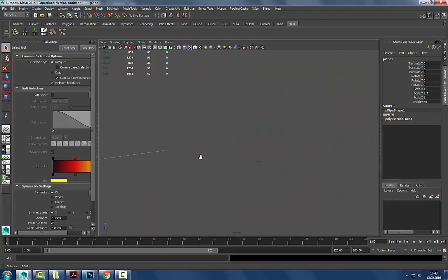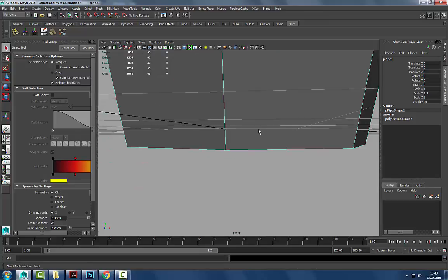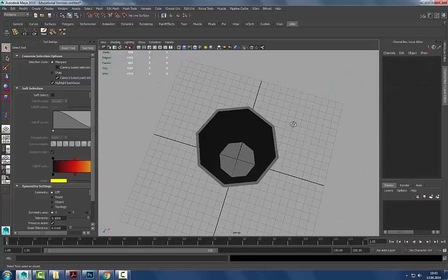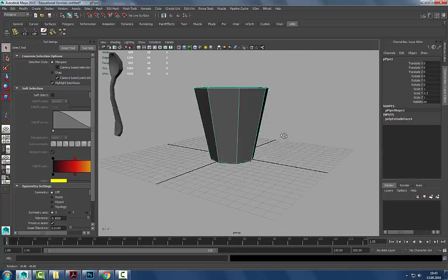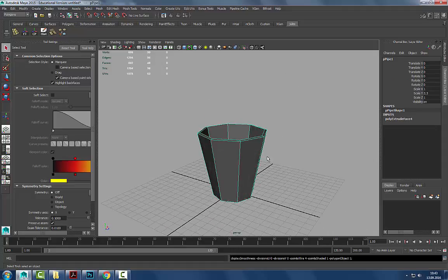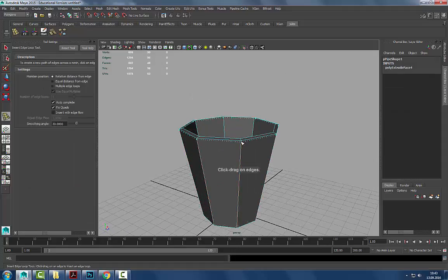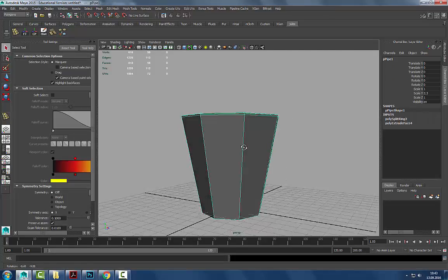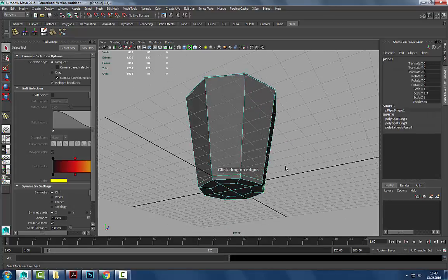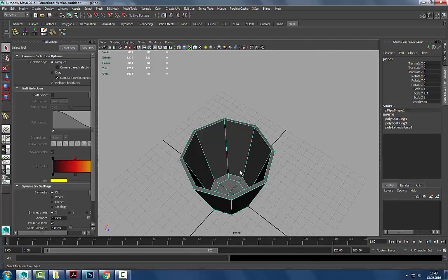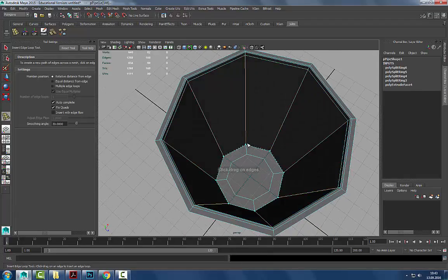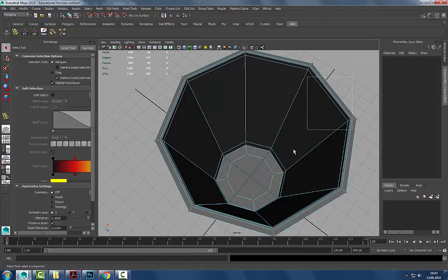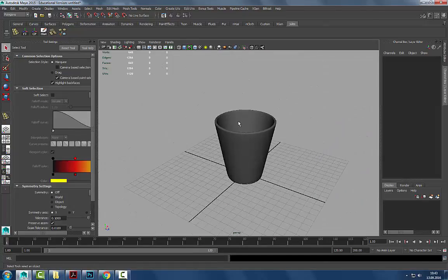Let's take a look inside. This is the way it works. So in this case, nowhere where we're looking at this cup are we looking at the back faces, right? It's an okay solution. When we subdivide, it's going to look like this. We're going to need more creasing edges up here. We need a creasing edge down there to keep that shape. And we need a creasing edge up here and one there and one down there. And there you go. Just to keep all those corners.